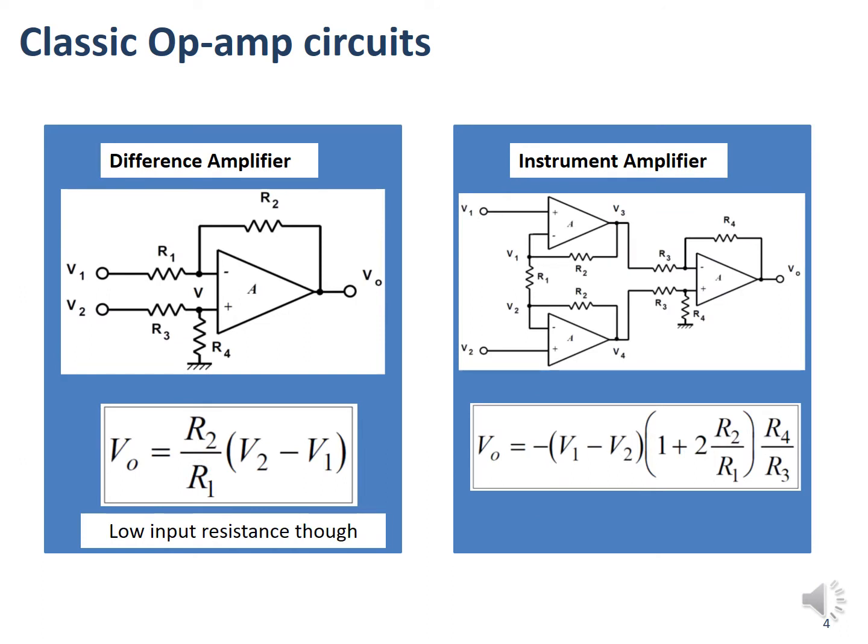And you should also be aware of these other forms of it. We've got the difference amplifier, where I've got two voltage signals applied, V1 and V2 now. V1 traditionally is placed on the negative rail, but you can change this around as well. You've got a slightly more complicated resistor network, but the V out is proportional not only to the ratio of the two resistors, but actually to V2 minus V1. So it amplifies the difference between V2 and V1.